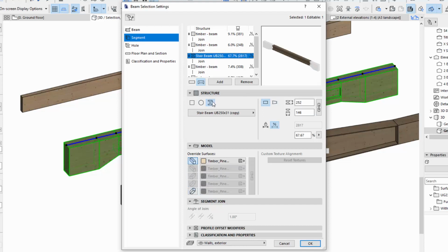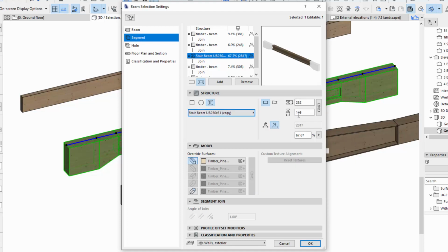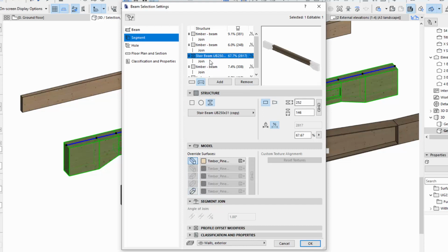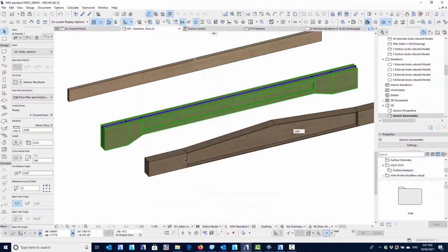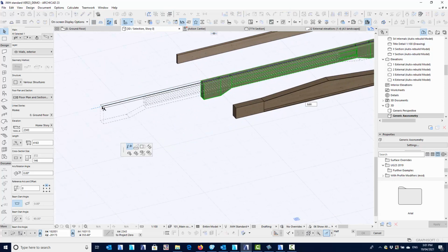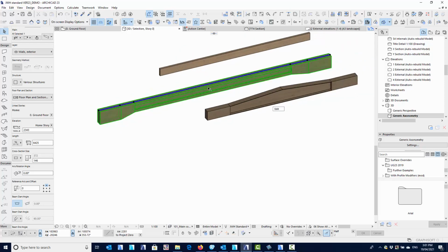It then joins onto a complex profile I-beam, and that happens to be that particular size. So the size of this beam happens to match the size of that end taper. We've got the complex profiles, and then it just repeats going back the other way, so we just have a tapering beam. So we have a segment section that's tapering, and then a regular segment that's not tapering, and they just all join together, creating that column. So you can see here now that when I stretch this, it's been set so that all of these will stretch proportionally, but the beam in essence stays exactly the same as it was before.